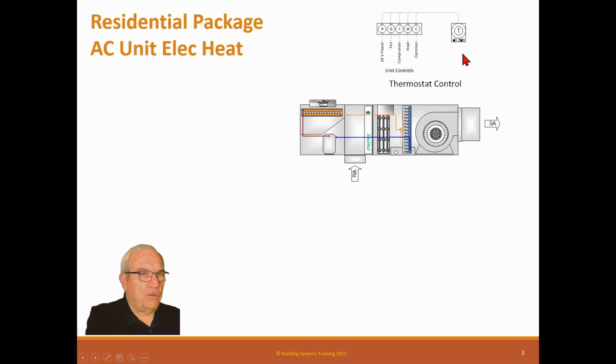Now, for most homeowners, they really need to have more than just a standard thermostat, because this thermostat only controls the unit to temperature. It doesn't matter time of day or what day it is. It's on or off based on temperature. Well, normally we want a programmable thermostat where we can tell it we want it on this time of day for Monday through Friday, and on this time of day for Saturday, Sunday, anytime. Most of them are 7-day time clocks where we can set different temperatures and different times a day. This makes it a little bit more energy efficient.